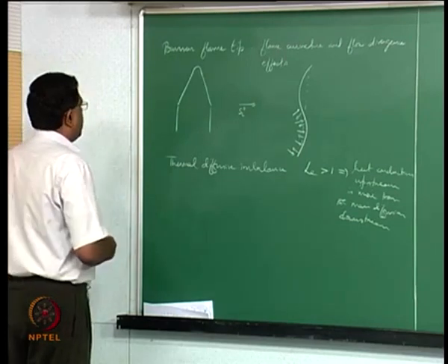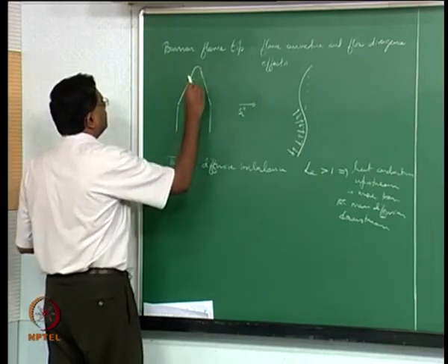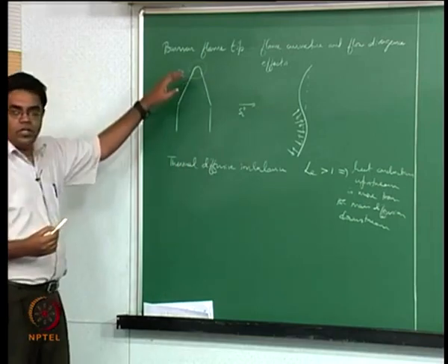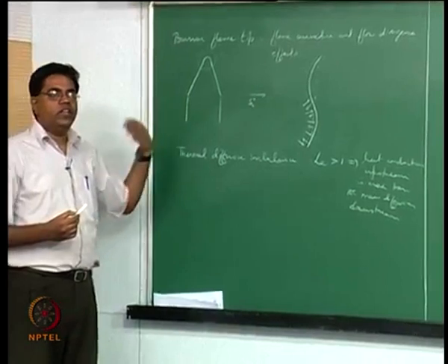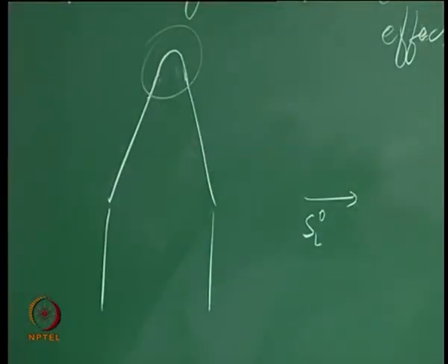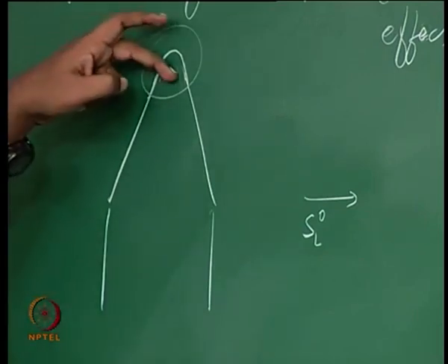So if you now think about what is happening at the tip of the flame for a greater than unity Lewis number, we expect a more intense burning, an increased flame speed that can try to match the flow speed there.